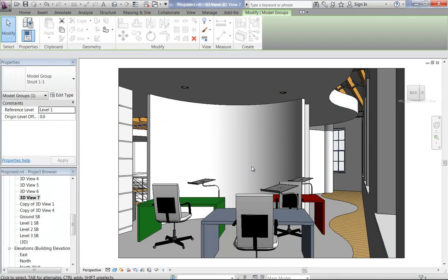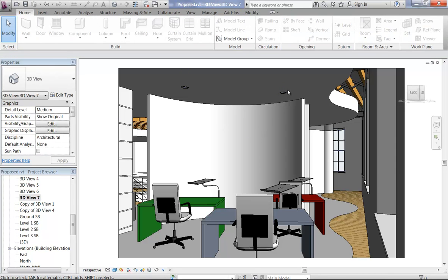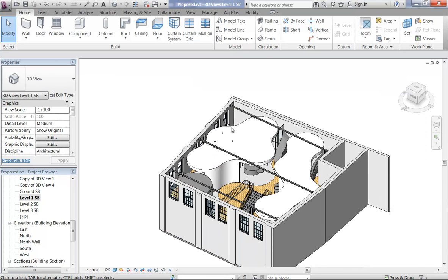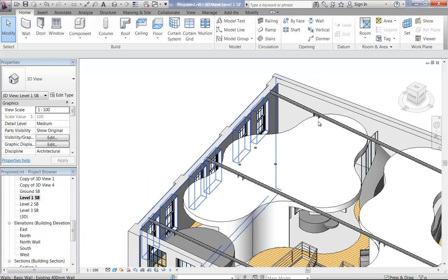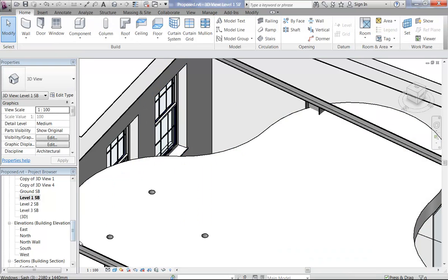So how did you make them work like that? Oh, okay, so I had to go in and edit the family, and I'll go into that in a moment. I will give you that family though. And so I'm just going to go now to a 3D view, so you can see my ceilings and the fact that they're maybe not typical. So these ceilings here, I just made using model in place. But as long as you set ceilings as the category, then you can place any ceiling hosted lights into them. Yep, it's fine. And so other than that, you've got a few basic kinds of lights.